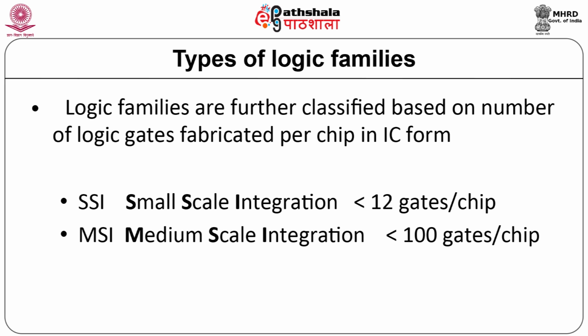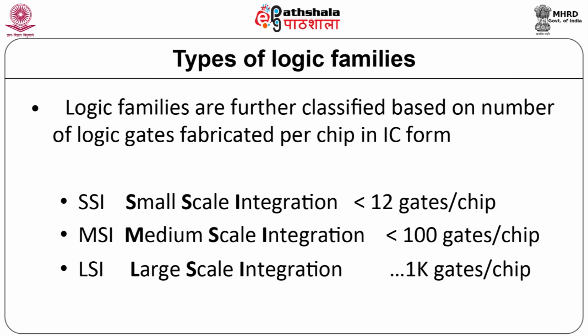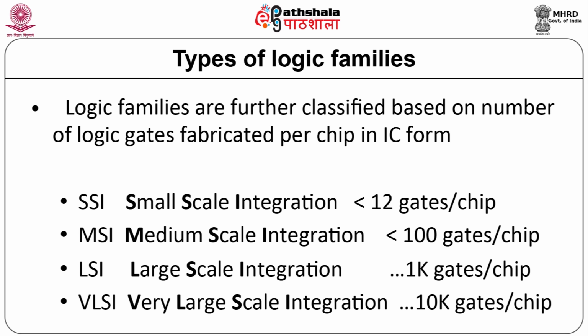If nearly 100 gates per chip, MSI, that is medium scale integration. More than 1K gates, then LSI, that is large scale integration. And more than 10K gates, that is VLSI, very large scale integration.